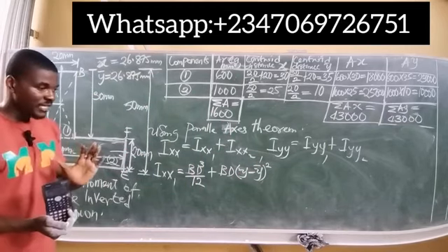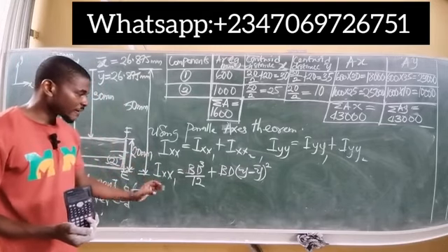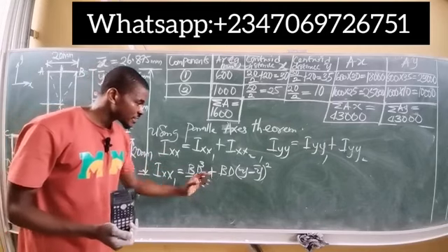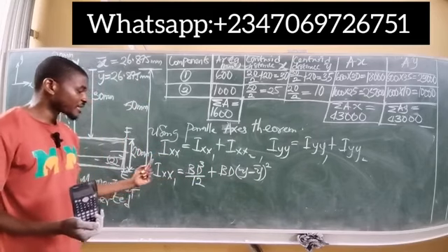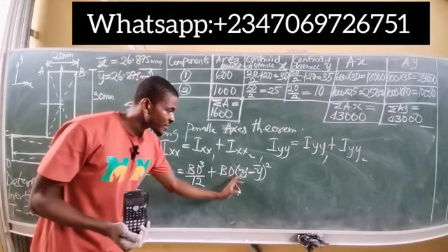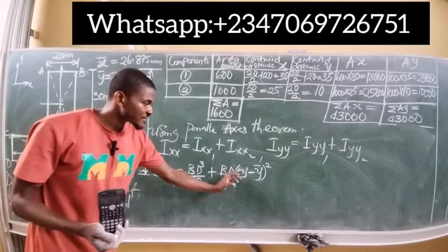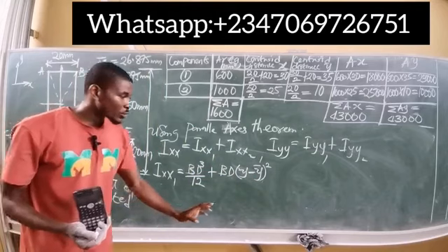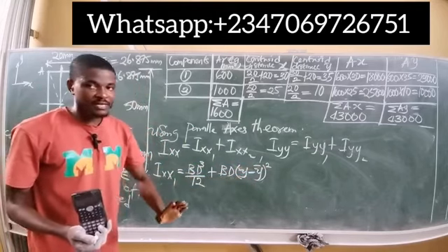So notice this transposition now. Since we are considering x, we have bd cubed over 12 for the first segment plus that same width times the depth of that same segment. But now, since we're talking about moments in the xx coordinates, we multiply bd by the difference between the central distance and the centroid in the y direction for that first segment. It can also be the centroid minus central distance. It doesn't matter, since it is squared, any negative sign will cancel.